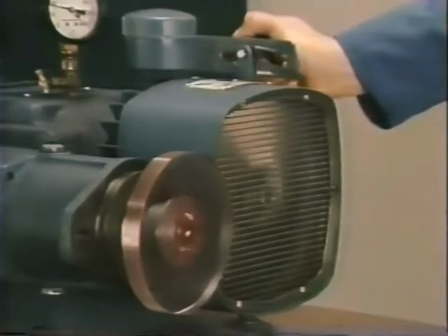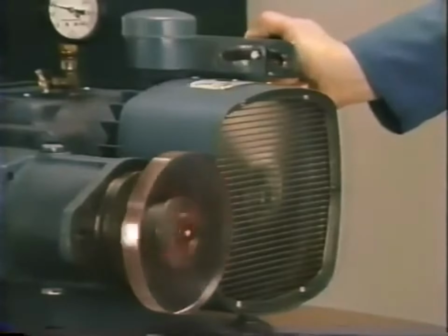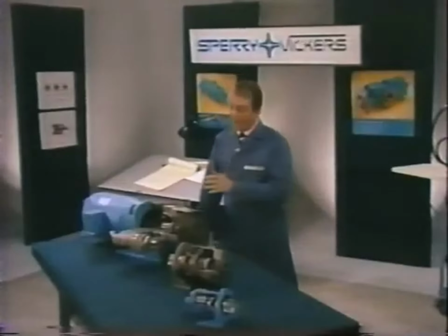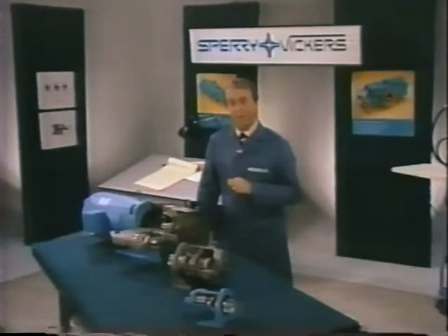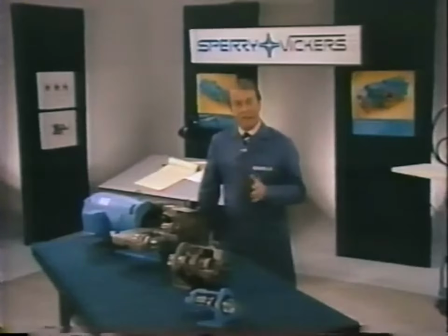Remember, the pump and motor in this unit have the same displacement, so the top speed of the motor would be essentially the same as the pump drive speed. If we were to install a larger hydraulic motor, it would develop more torque, but since it would require more fluid per revolution, its top speed would be slower. A smaller motor would, of course, turn faster, but develop less torque. In each case, however, the torque would be independent of speed.